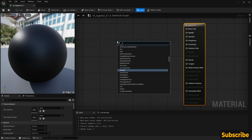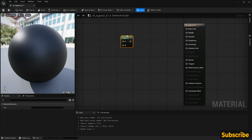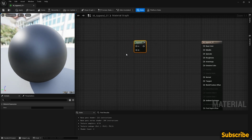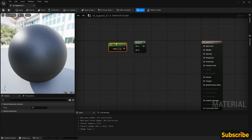So I'm going to open this up, and we're going to take a look at what the append node does. If I right click and type in append, you can see I can append many, append vector, append vec4, append vec3. Let's just do append vector. So we might ask ourselves, what is this and why would we want to use it? Well, sometimes we'll have, let's say, a scalar or a constant. Let's type a constant in here.